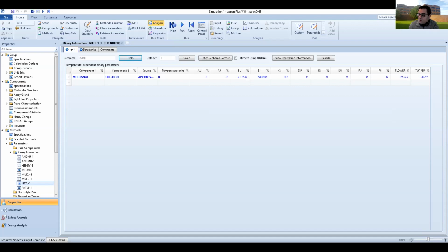And in the tutorial, you're also being asked to deal with this binary interaction error. This is a common error. You just need to keep an eye on it, because if you go to simulation and keep getting errors in your simulation, sometimes it's because of this very simple thing. Okay, so this is done.